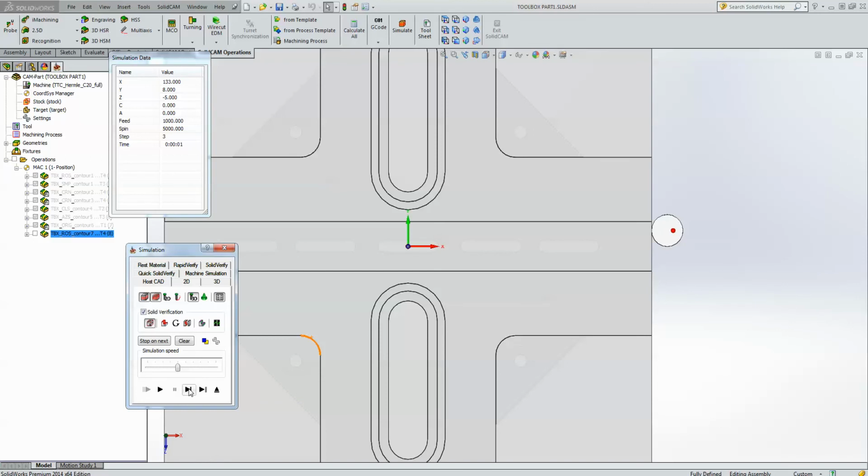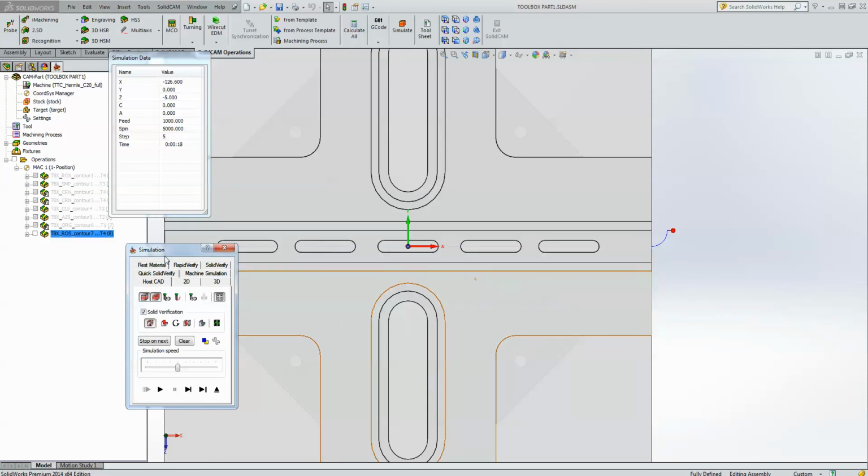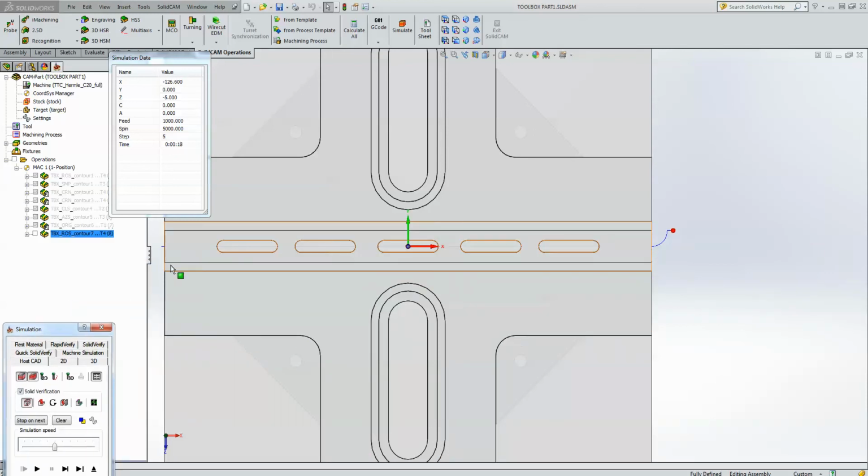And by the way, in the G code, you'll see G1 as it goes from here to here. And now it's going to actually roll in. Let's do away with the tool so we can see the actual tool path. You can see now that it rolled in to this point. Then it just goes across to the other side as shown over here. And that's all done. Let's see this together with the tool itself.